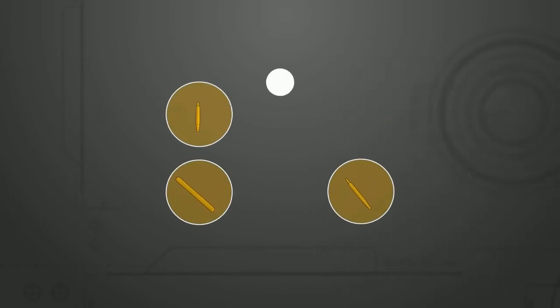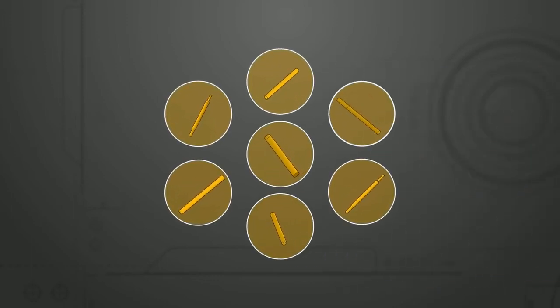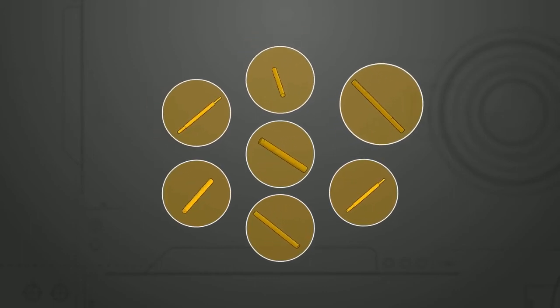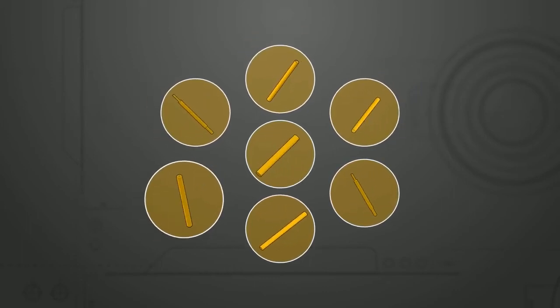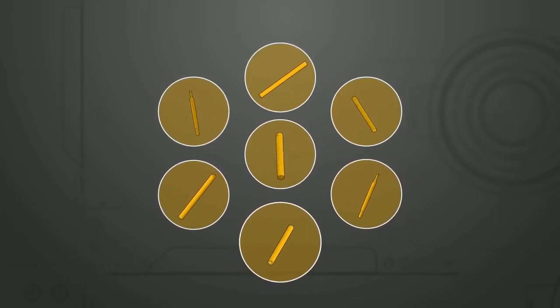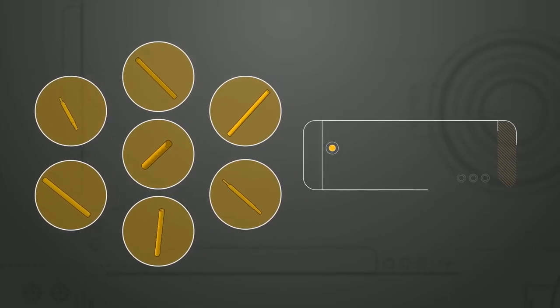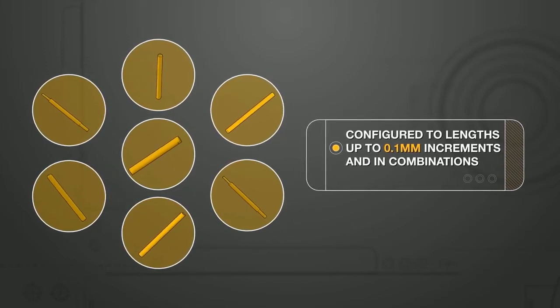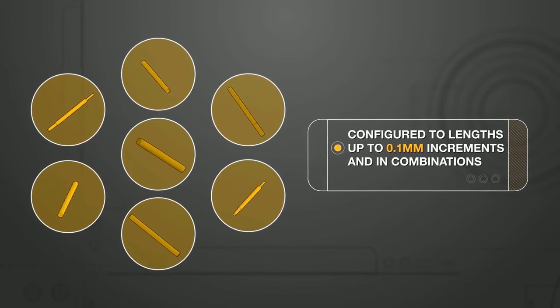MISUMI rotary and drive shafts can be configured with a variety of alterations, including threaded, tapped, D-cut, hex hole, wrench flats, stepped, and hollow. These alterations can be configured to lengths of up to 0.1 millimeter increments and in combinations to fit your application needs. This concludes the series on shafts.